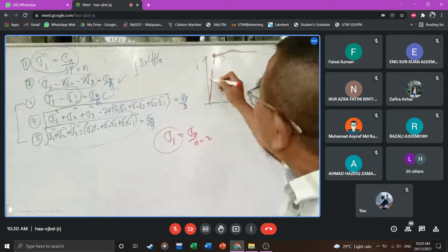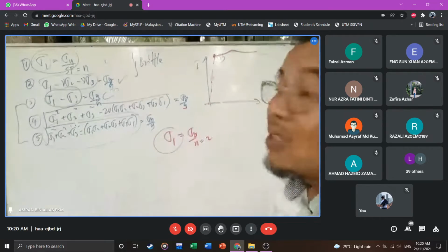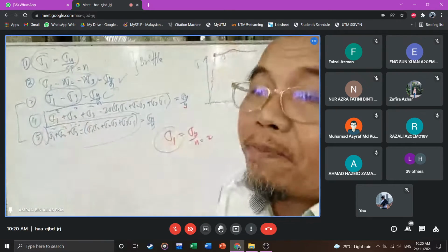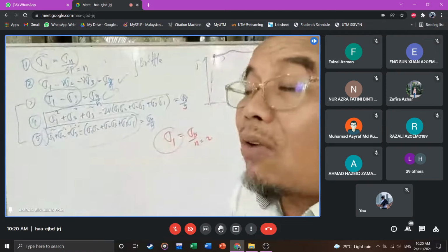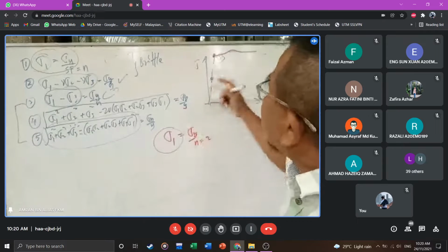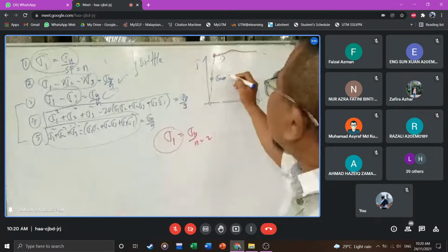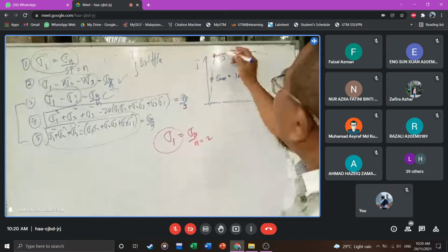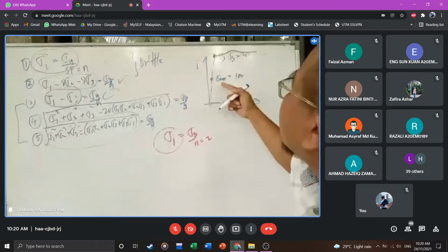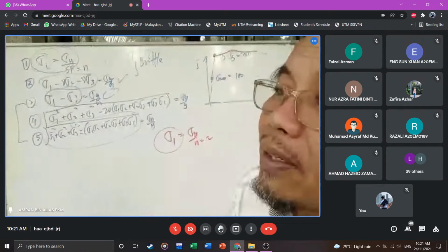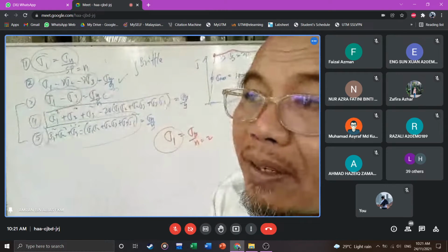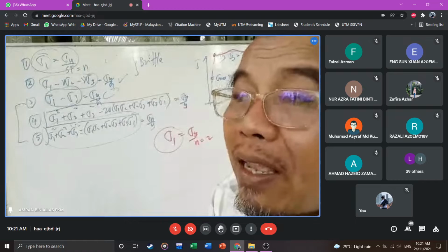When this is 2, so this is halfway down. So that's the meaning of safety factor of 2. Double to failure. Are you with me? Yes. Your maximum stress, sigma maximum there, is equal to 100, and the yield there is equal to 200. So how many times more to fail? Double. That's the meaning of safety factor. Are you with me? Yes.